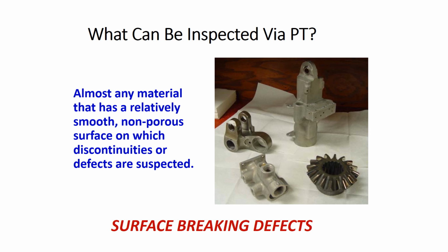So if you go to magnetic particle testing, it requires some kind of shape and size constraint. But for PT, this concept doesn't work very much. Almost any material. And the second thing is that very heavy parts, for which other NDT methods face difficulties in inspection, penetrant testing easily handles, or you can say penetrant testing can be easily applied on these parts.